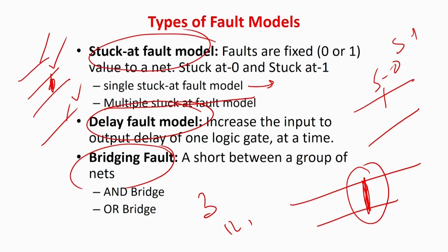This was actually a path-breaking optimization in the area of test. Whenever we moved from low scale integration to medium scale integration, and then to high level integration, that is VLSI, we all moved to fault models. Nobody could do functional or structural test at that level because of the complexity. Fault model was a phenomenal discovery: statistically it is shown that if you verify on the basis of a fault model, mainly the stuck-at fault model, there is a very high probability, 99.9%, that the circuit does not have any functional